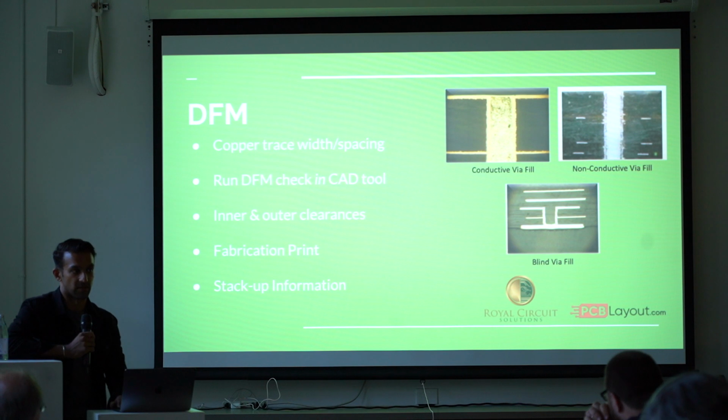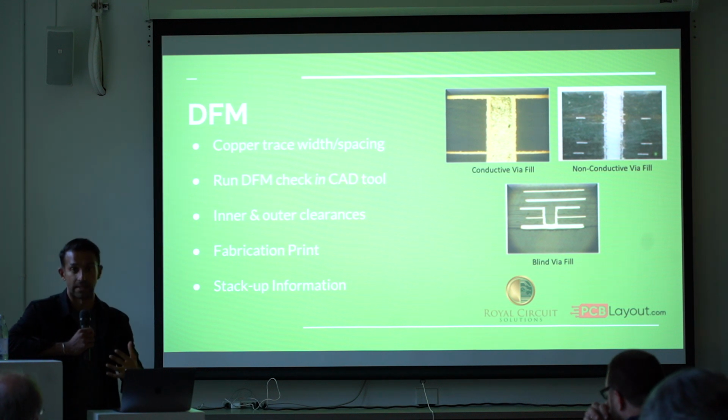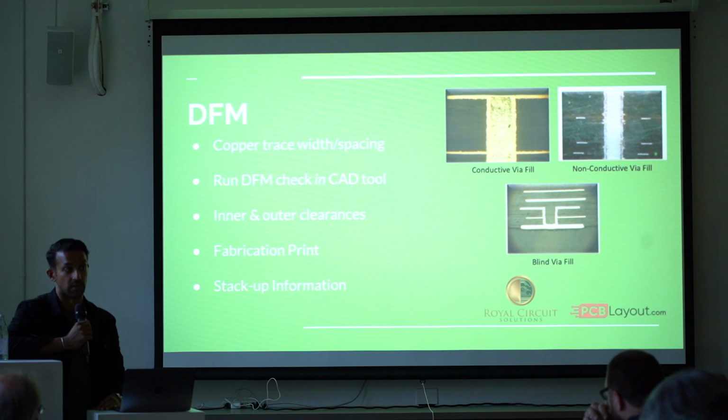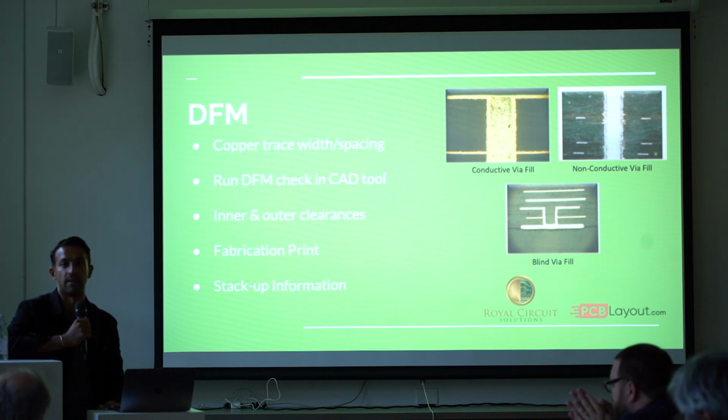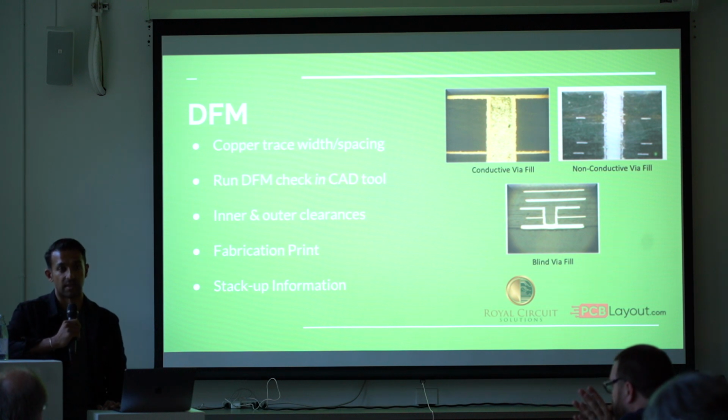The one thing that we do, there's only 2 shops in the country that really do it, and we're one of them, which is copper fill vias. This is a new technology that a lot of, especially automotive customers are taking advantage of. We literally fill the whole thing with copper, essentially through a plating type process. And you get really, really good thermal dissipation through these vias. There's a limit to it. I don't have the exact aspect ratio. It's not very large. But especially for via in pad and some kind of heat sinks, it can save a lot of space on your board by getting rid of those components, and you do these copper fill vias in adjacency with each other.